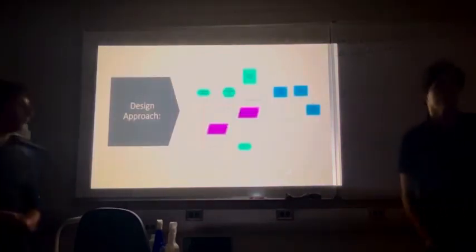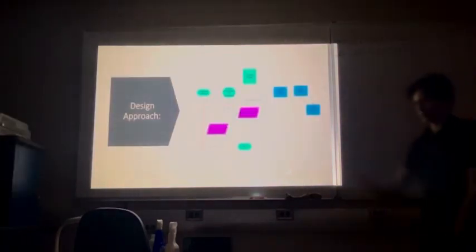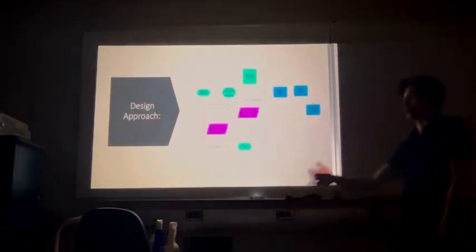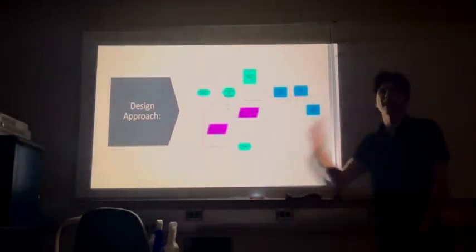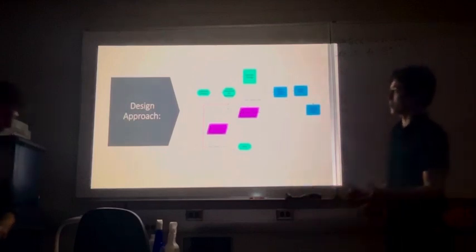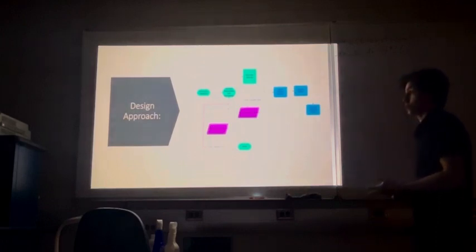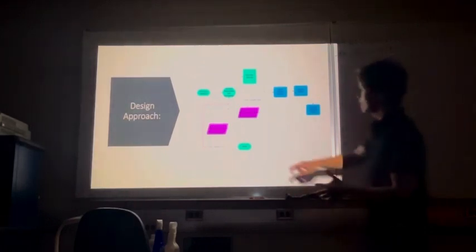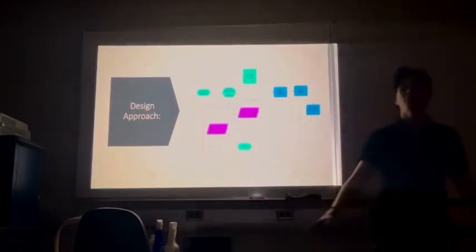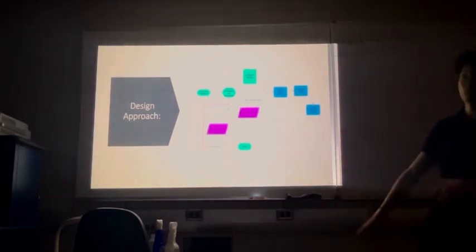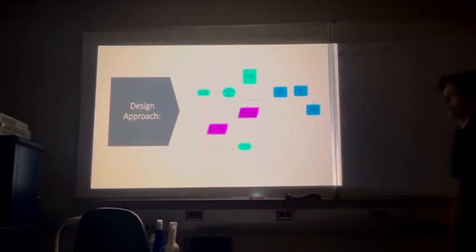So when you come across this problem, like Daniel was mentioning, we have all these frequency partitions that we've chosen, but there are so many different ways to approach this. Our design approach for every single filter is, we choose which frequency and bandwidth we're going to design around. We set those, and we pick a filter topology. We went through so many filter topologies: Sallen-Key topology, multiple feedback topology. We even touched on some state variable topology, which we'll get into later.